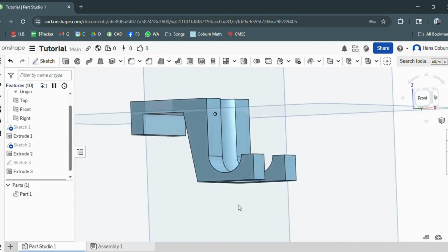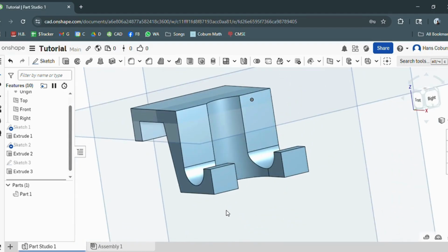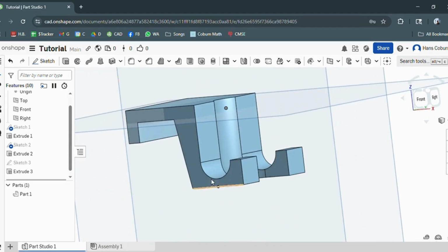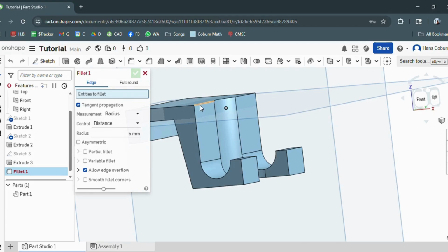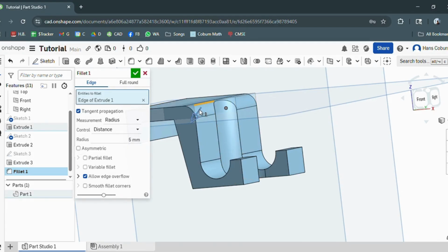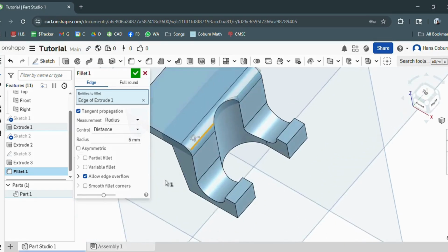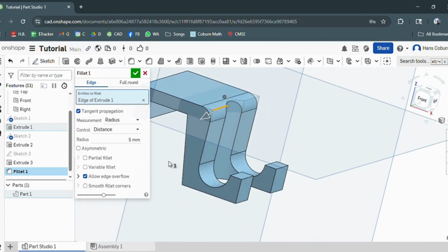Okay, now there's some stylistic things you can do to sort of pretty up your 3-dimensional object. The first one is fillet, and you just click on an edge and it'll cut away at a circle. It's doing it at a circle with a radius of whatever this number is. Right now it's taking away 5 millimeters.